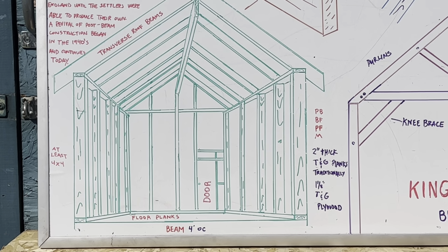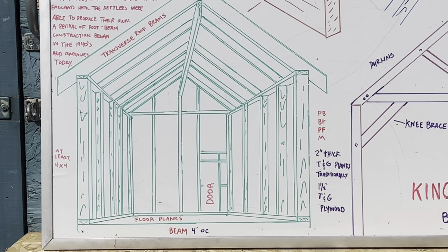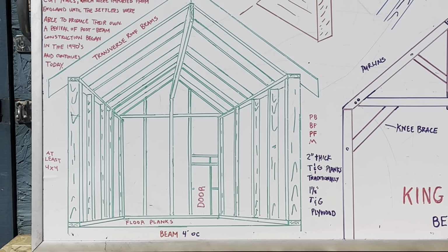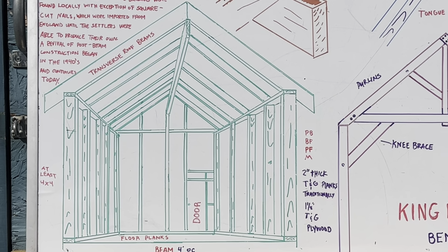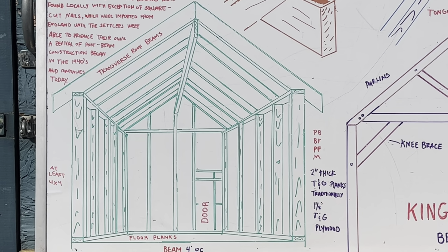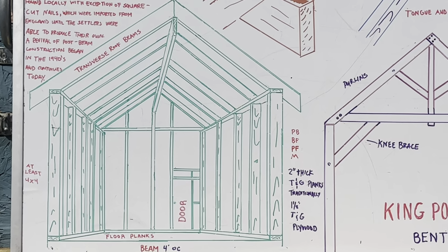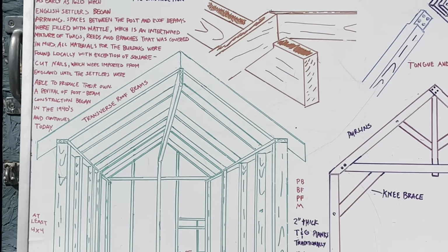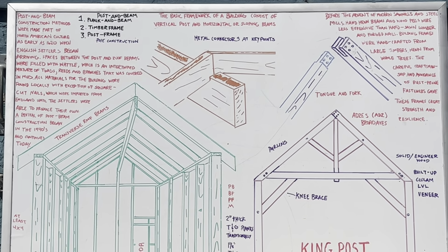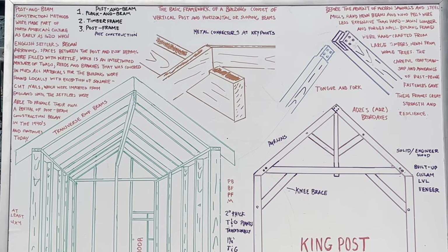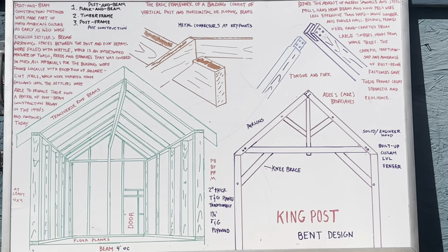Oh, what I want to say about the hand-hewn beams, of course, a tree is normally round, right? So if you're going to hand-hew a beam, you can use a broad axe. I've seen someone stand on a tree before and then hew it that way. What you're basically doing is squaring the sides off, making them relatively flat, or rough, flattening your four sides. Now, people still use these hand-hewn beams today.